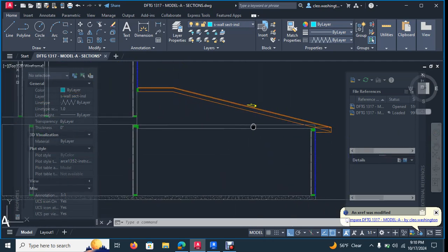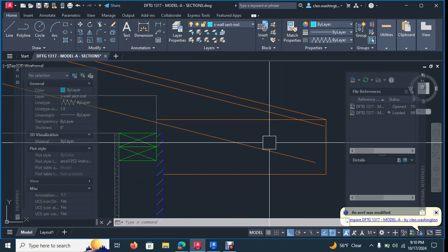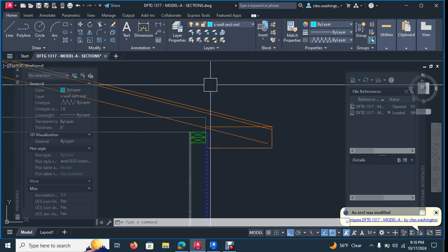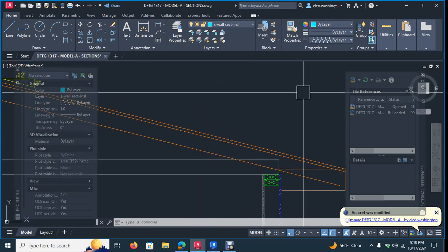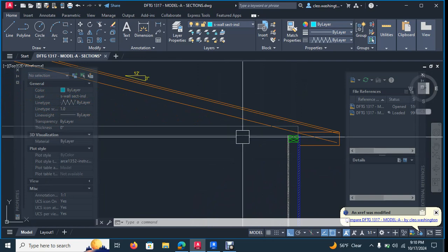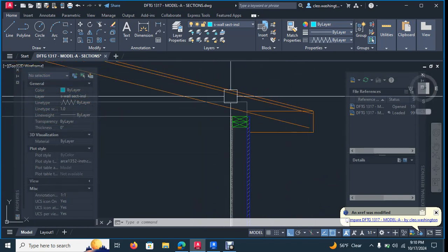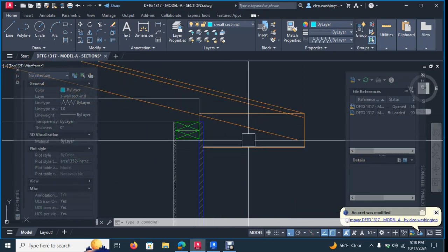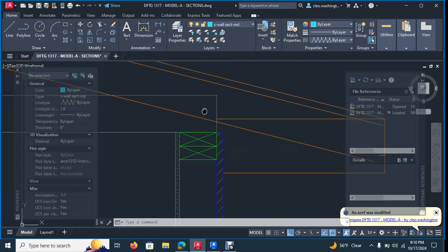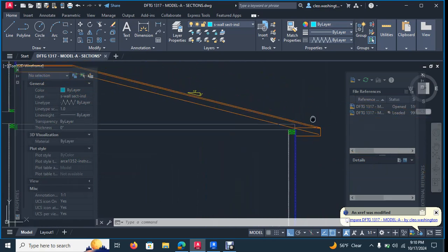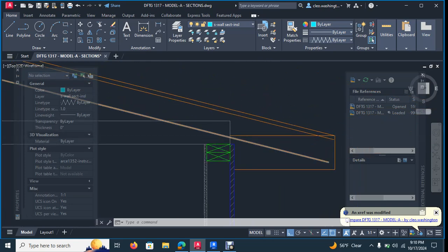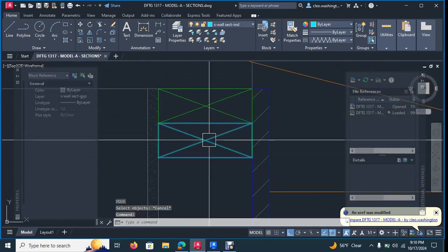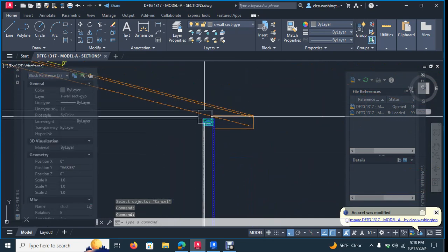First things first, this is what's known as an eave detail. There are two types of eave details. What I want to do is clean this up first, because we're potentially going to have to raise this roof. So let's move these guys up some. Select these two, and we'll give it a new plate height here.